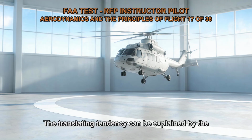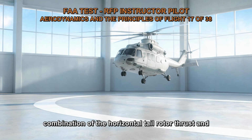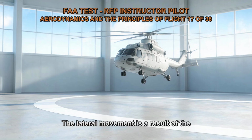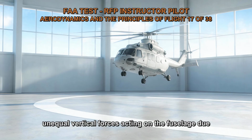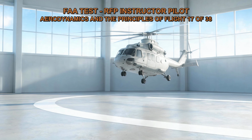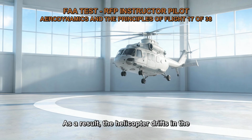This horizontal thrust force creates a tendency for the helicopter to move laterally in the direction of the tail rotor thrust. The translating tendency can be explained by the combination of the horizontal tail rotor thrust and the helicopter's inherent stability characteristics. The lateral movement is a result of the unequal vertical forces acting on the fuselage due to the offset center of gravity and the tail rotor thrust. As a result, the helicopter drifts in the direction of the tail rotor thrust.